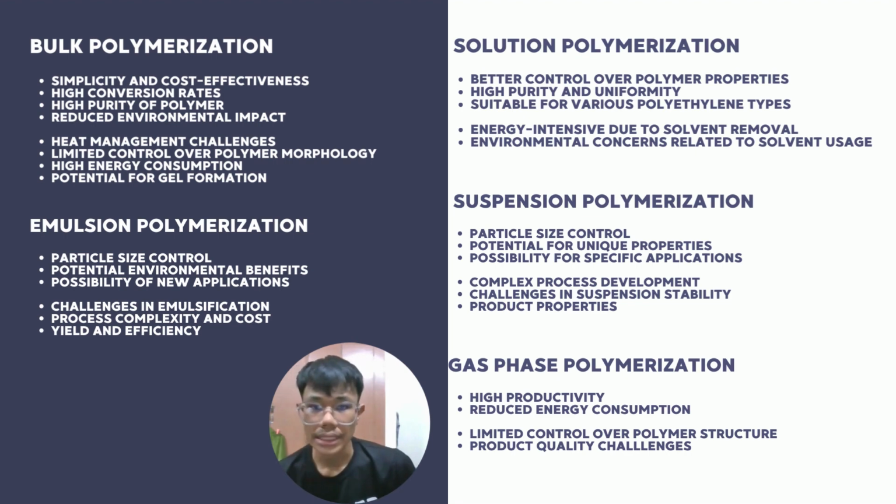For solution polymerization, the strengths are better control over polymer properties, high purity and uniformity, and suitability for various polyethylene types. The weaknesses are that it is energy intensive due to solvent removal, and environmental concerns related to solvent usage.